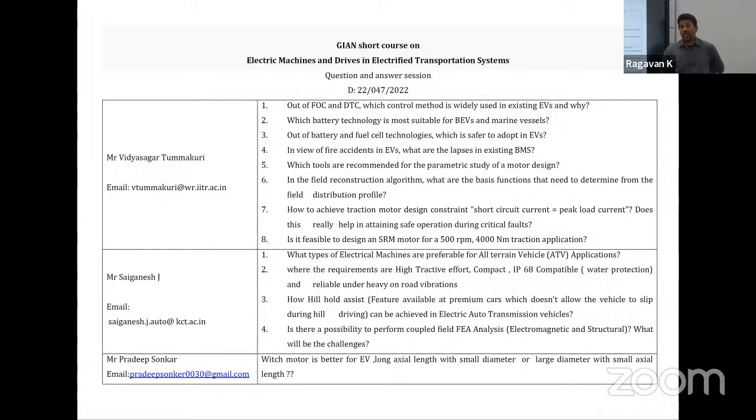SOH connects very nicely to state of charge, but including terminal measurements, you need to find a good way to identify what the BMS is going to do. Oftentimes, BMS tends to be an on-off system, meaning something goes wrong, you turn it off. Now the BMS, the way we are designing it right now, and I have an existing patent on that, was estimating the thermal state of charge for a lithium-ion pack, and specifically using that to create a framework that allows you to monitor temperature at the same time as you monitor state of charge. So it has to be a combination of electrical plus thermal. If you don't do that, I think you are always going to be missing something.